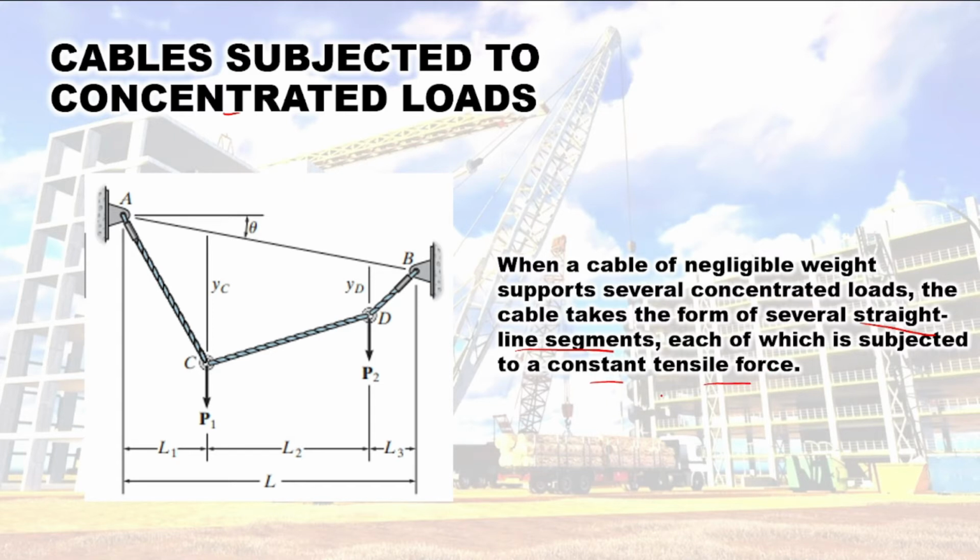So again, ang cables natin, this is very strong for tensile forces, but very weak in compressive forces. We always assume that our forces there are tension. We do not assume cables as compression kasi again, ang cables natin hindi kayang bumuhat ng compressive force. Okay? So, pag ganito, we have concentrated loads, ang tendency ng cable natin would become straight line segments. For example, ito, you can see na concentrated load to, concentrated din to. So, yung mga cable natin dito would become straight lines.